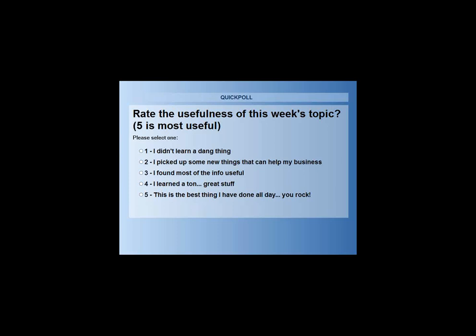All right, so let's see. Joe typed in, if I have staged gas heating, can I do staged airflow in heating mode? In concept, the answer would be yes. In practice, you cannot do it on a standard unit because you don't have any way to change the economizer positions as you change the airflows, because the economizer can only handle 2 stages of airflow. Additionally, most of the manufacturers have not yet published data on how much airflow they expect for each individual stage of heating.